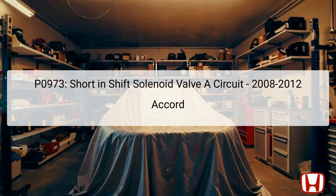executing gear shifts. This solenoid is found within the transmission assembly, and any faults in its operation could adversely impact vehicle performance. It's crucial to address this DTC, as it may imply either an ongoing electrical fault or possible future mechanical failures if left unresolved. Ensuring that all diagnostic data, such as freeze frame data, is recorded and analyzed prior to beginning the troubleshooting procedure also helps understand the condition of the vehicle during the incident of the error.